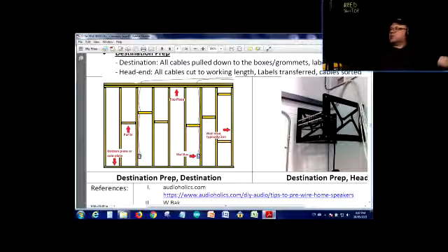Quite often you're just going to leave them coiled in the boxes, and there's going to be one other sub stage of coming in and doing the final termination. But at any rate, you're going to have 2 people. That's the best thing. That's more efficient. 1 person hits the field and terminates all the jacks in the field using the same tools repetitively. And there's another person that goes to the head end.